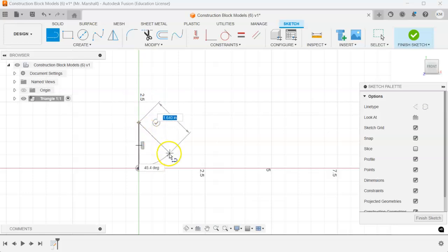I'm going to go ahead and create this triangle's hypotenuse and drag it down here, and I'm going to use these object snaps. Notice that as I pull my cursor down, it yanks over to that x-axis, and that's called an object snap, and that is my friend. I'm going to let it pull me down to that x-axis and click somewhere randomly down here. I'll left click and release again.